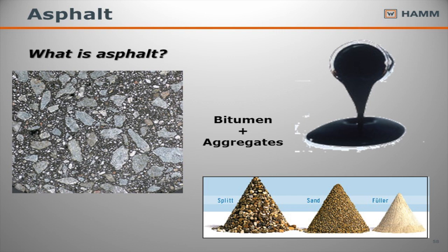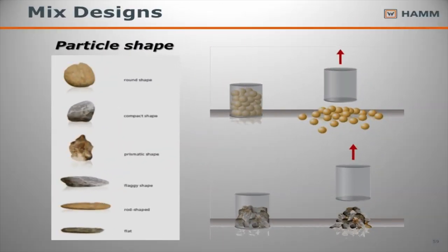So what is asphalt? It's basically just a combination of different sizes of rock, sand, and filler with some kind of an oil. And there's a variation. We don't want to have all marbles in there because it'd be too easy to compact, and we need to have some kind of resistance for the type of equipment that we have going over our roadways. We also don't want to have 100% fractured material because now when we compact it, we have a chance to break it. If we break it, it opens up and exposes that rock to moisture. We get moisture in there, in between the rock and the oil, strips the oil off, we have a pothole. So we want to have the right combination that gives us a good compaction effort. We also want to make sure our texture and our flat and elongateds are eliminated. But that's a whole other story when you come to talking about mix designs and what we can and cannot put in it.